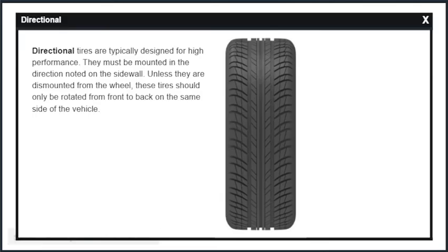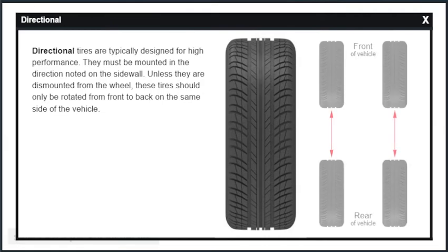Directional tires are typically designed for high performance. They must be mounted in the direction noted on the sidewall. Unless they are dismounted from the wheel, these tires should only be rotated from front to back on the same side of the vehicle.